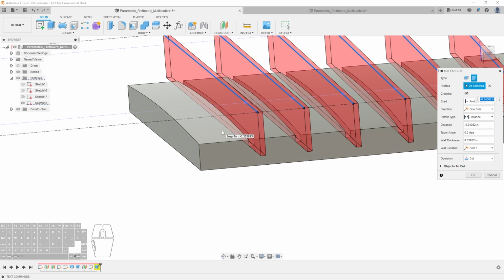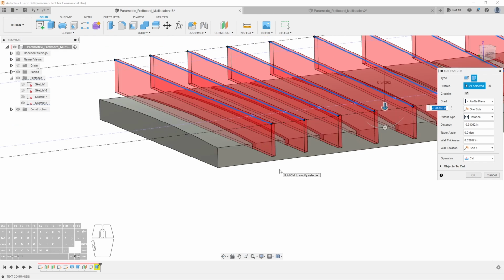This is the reason why I mentioned right at the start that maybe we don't cut the fret slots, because the fret slots aren't really that useful for us. They are more of a visual thing, so that we can develop better renders. When you're actually doing the CAM for fretboards on your CNC, they're not particularly useful. I will show you how to create a different sketch that you can use to do the CAM for your fretboard. But if you want to have this feature where you can define whether your frets are hidden tang or through tang, then with a compound radius fretboard you will have to do a flat bottom fret. I haven't been able to solve it otherwise.